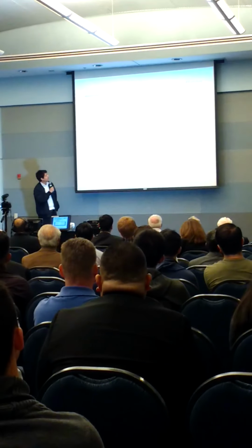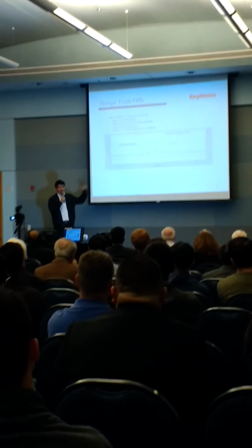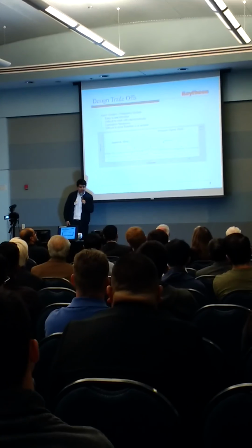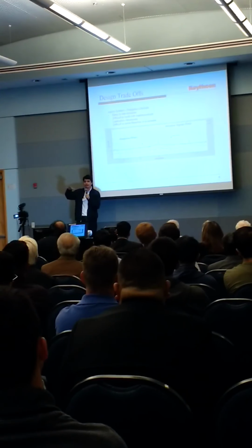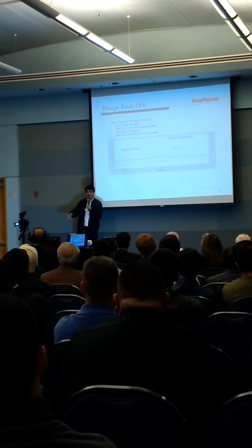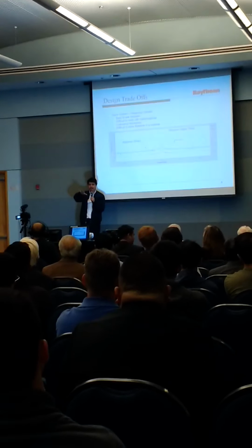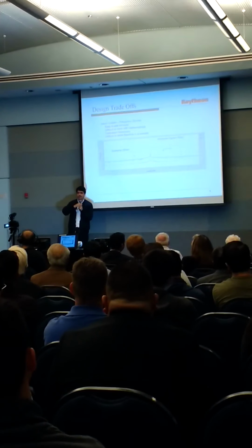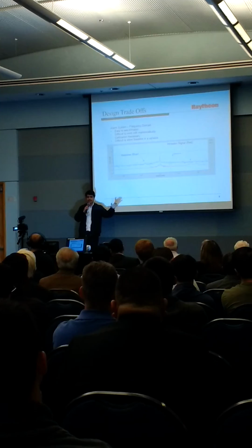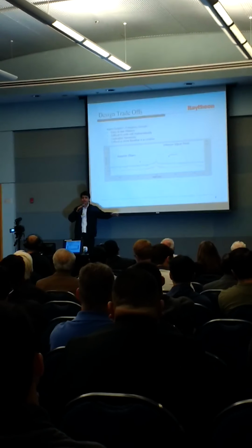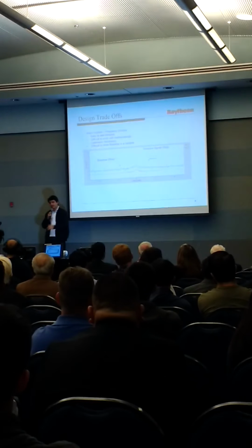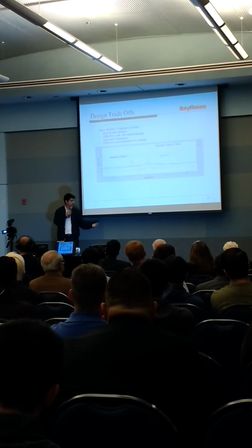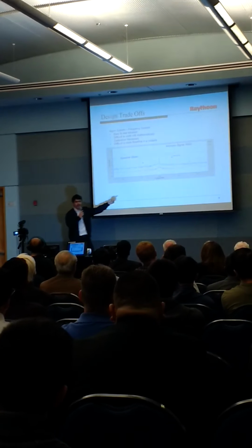Next slide. So how do we make an alarm? Before we make an alarm, we have to get a baseline. A baseline is basically the environment, like Wi-Fi, your cell phone, all of that. We have to get the amplitude of all the signals so that those don't cause an intrusion. Those are the environment. So we do this either in frequency domain or in time domain. In frequency domain, it's a lot easier.